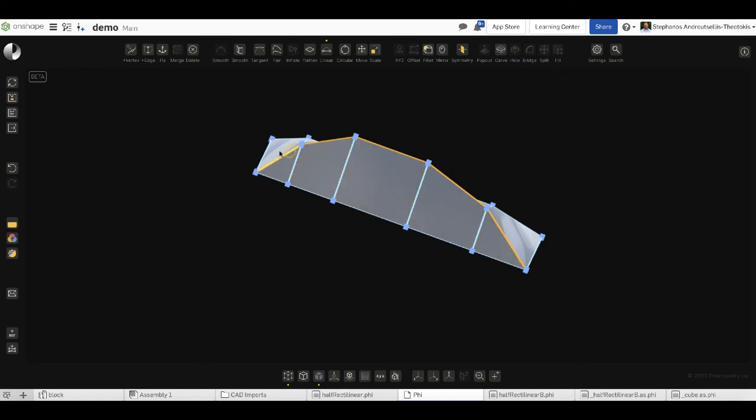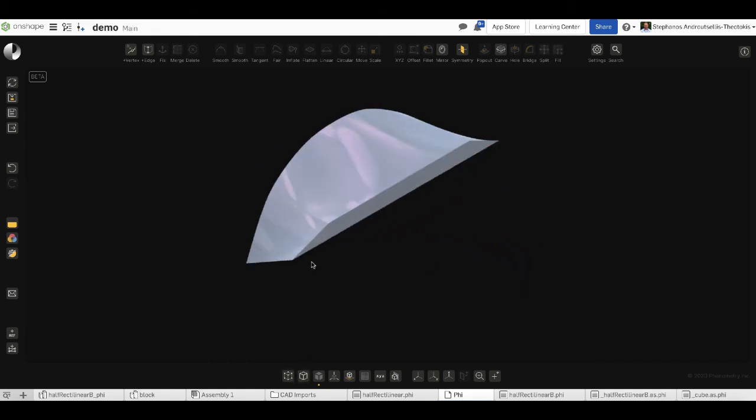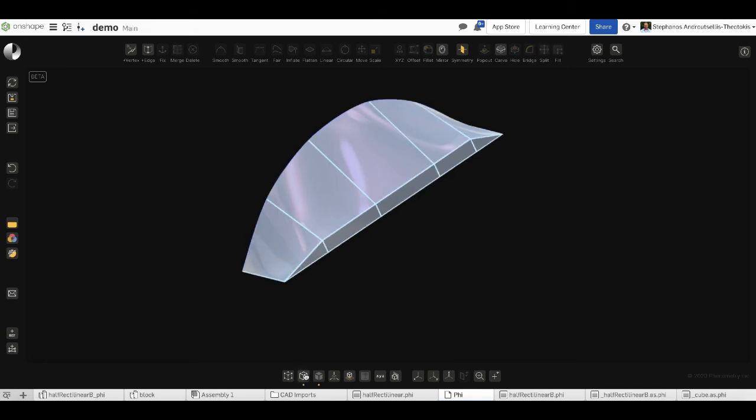Now, I have selected this chain of straight edges, and by fairing them, what I can do is basically remove freedom from the entire chain. So I simplify it. If it were a B-spline curve, I would be, I assume, removing control points or something like that. So that in the end, I'm left with a very smooth, elegant, let's say, and simple shape. And so you see that we have a set of straight edges that go from sharp corners in this case to a completely smooth object.